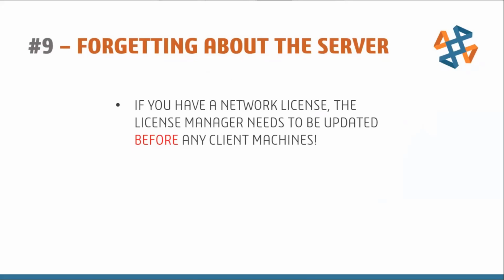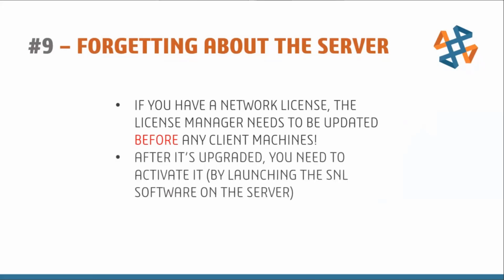And that could, in this year, require a server upgrade as well, as we saw in the very first one, number 1, upgrade without testing. So you always have to upgrade your network license manager, and it needs to be upgraded before any of the client machines, or the client machines will not work. That's it. So it has to be newer.